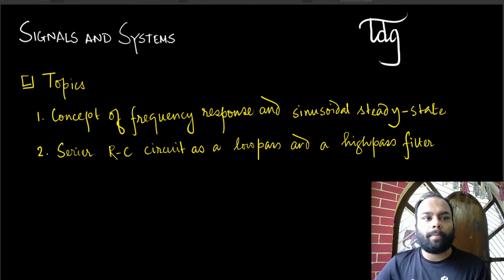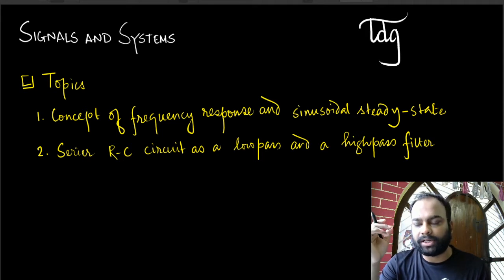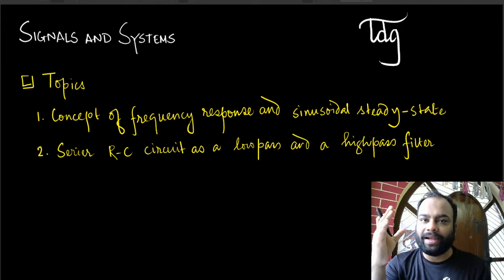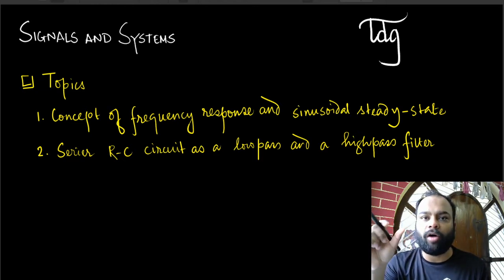So today we are going to talk about how we apply Fourier transform in analyzing electrical circuits. I believe we ended our discussion in the last class with that. We actually saw how the impedance of capacitors and inductors can be derived directly by the application of Fourier transform in electrical circuits. So when you represent impedances with an expression that involves something like j omega, what you are doing essentially is representing the Fourier transform of the circuit, right?